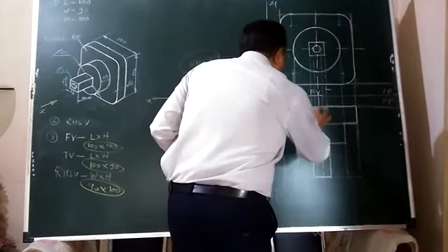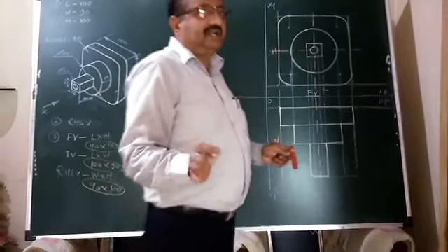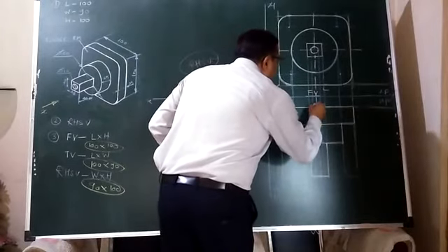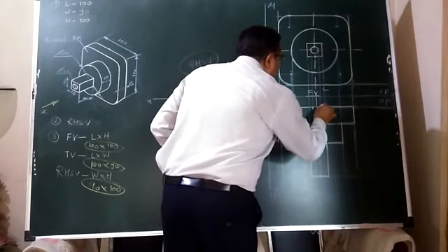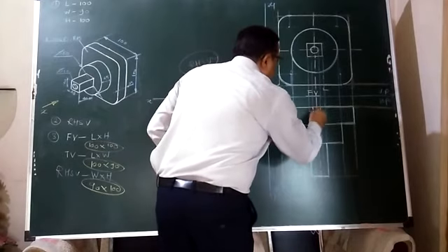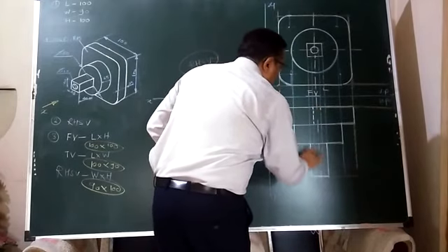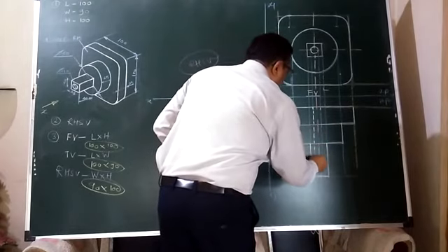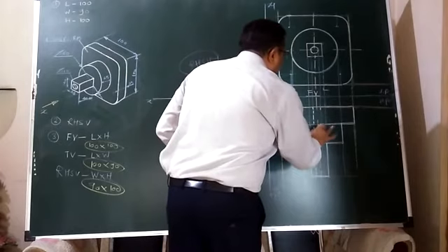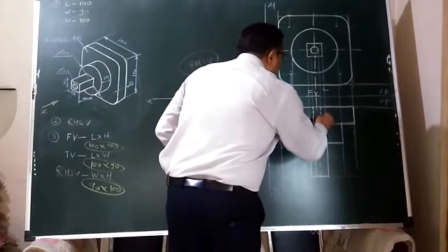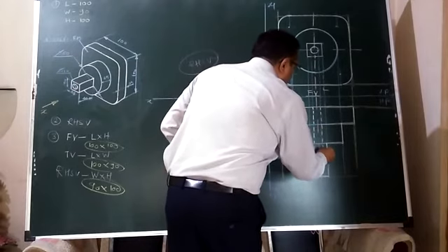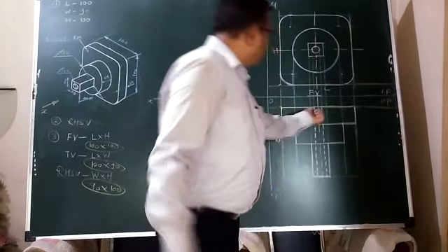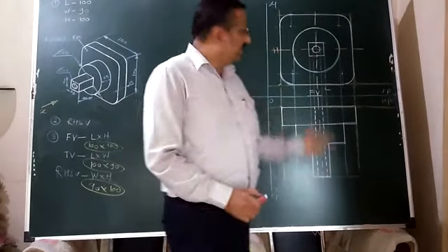So right from here, that too we have discussed: when depth is not mentioned, one should consider it is truly drilled. So the dash medium thick lines should run right from this back surface up to this front surface. Dash medium thick lines one should show in this way. Those projection lines you have to convert into dash medium thick lines. So this is nothing but those dash medium thick lines departed 10 mm. What those are reflecting is that there is a truly drilled hole in that object.